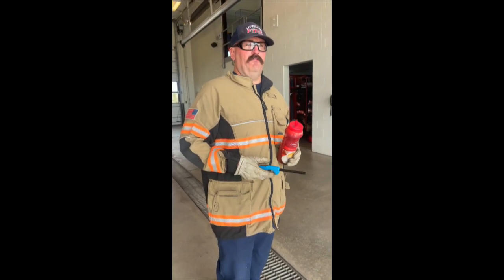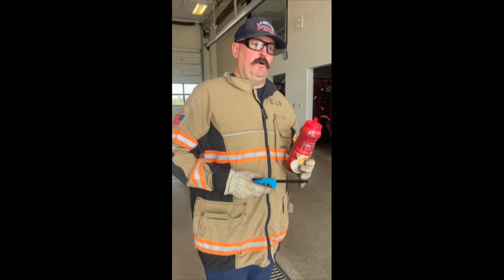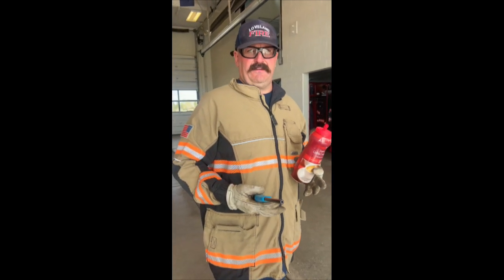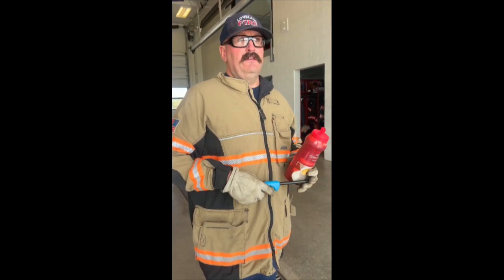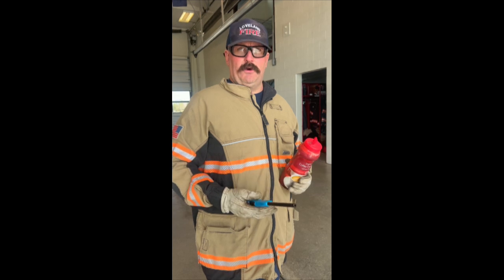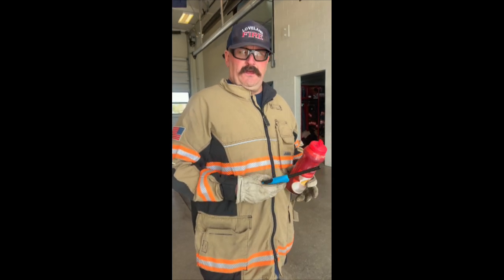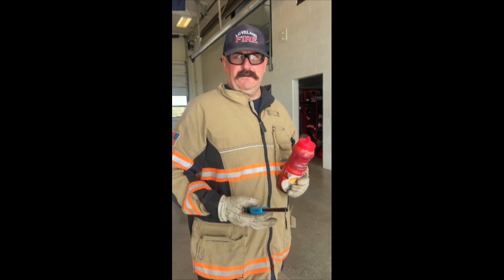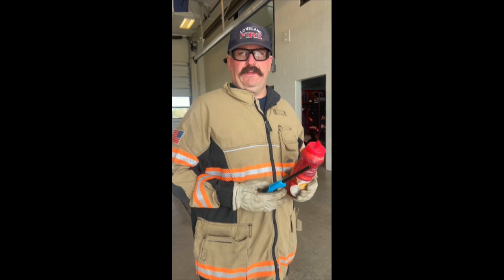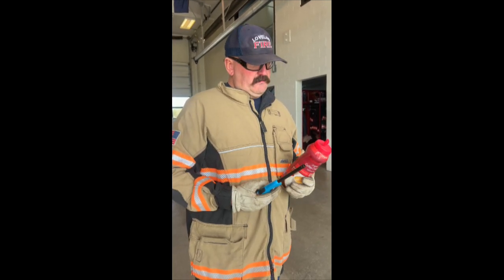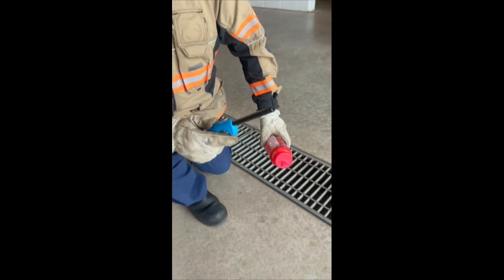So another aspect of air monitoring, or whether or not a product in a tank will burn, is dust and a dust explosion, and something we should consider. Not something we can readily monitor for with an air monitor, but something based on the product that's in the tank we may be working in or that has been in there, and the visual indicators of whether or not there's dust present. So in this case, it's coffee creamer.